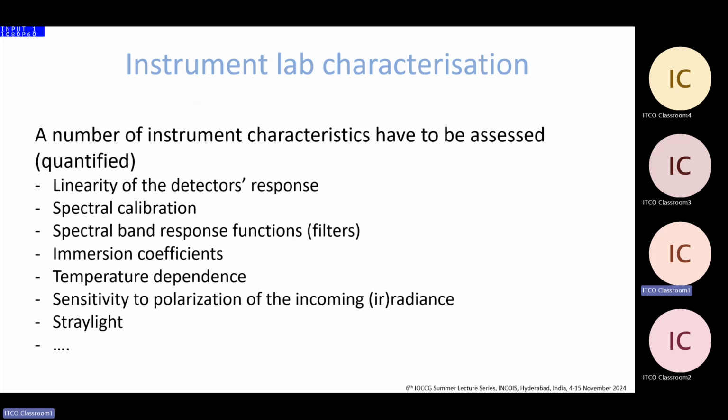Secondly is a spectral calibration. So what wavelengths are you actually collecting? Have you got a filter in front of it, or is it a diode array which is using a diffraction grating, and that will have some type of finite spectral resolution?